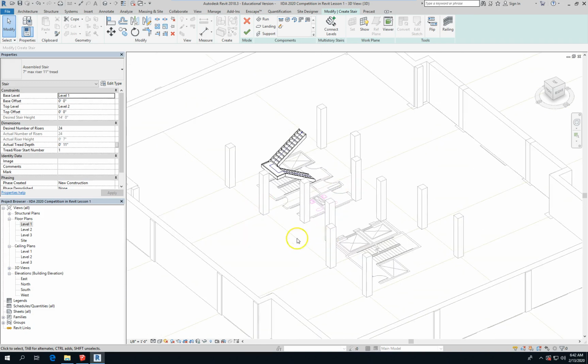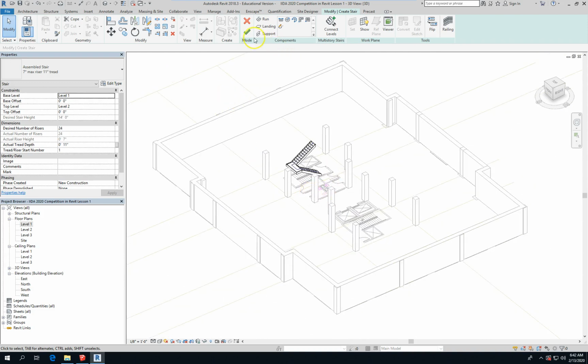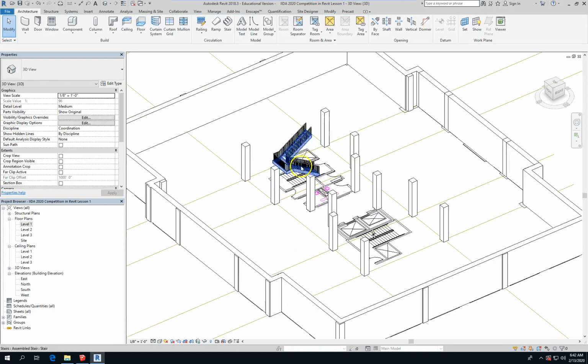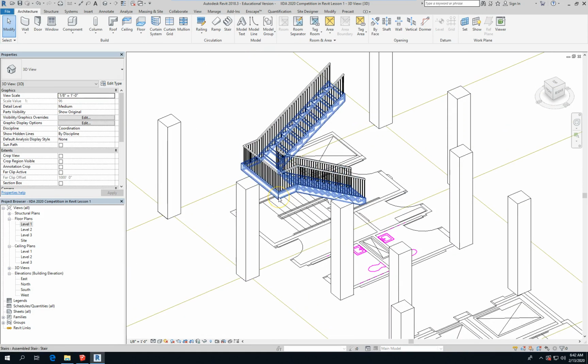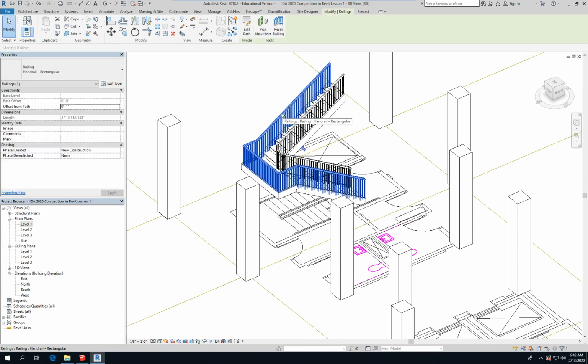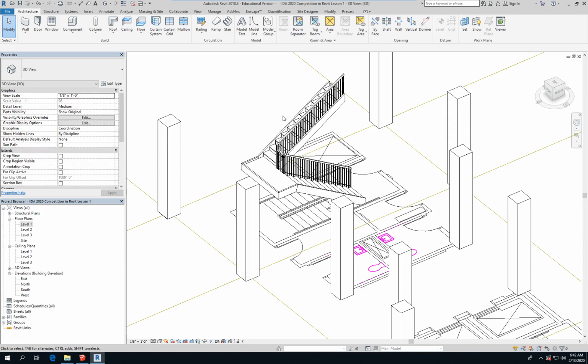There are more organized ways of drawing stairs, but basically the automatic stair, the stair by run, you can do it by sketch as well. And when I finish sketch, it puts in these hideous railings, one of which you'll delete because against the wall you don't need a picket railing, right? You'll have a pipe mounted to the wall, presumably, or something maybe more elegant.